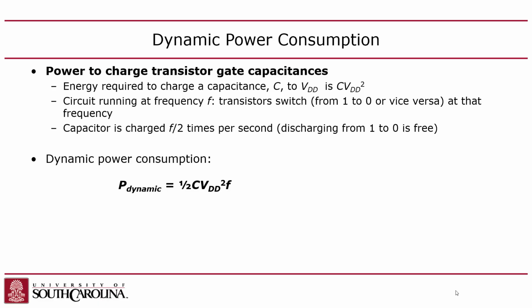And the threshold voltage, the voltage that actually turns the diode or the transistor on, is basically fixed. It really hasn't changed in decades. It's like 700 millivolts. It's changed slightly, but in silicon semiconductors, it's very hard to change the threshold voltage. That hasn't changed much, right? So basically, anyway, that's CV squared. You can change the frequency, but that's only a linear relationship.